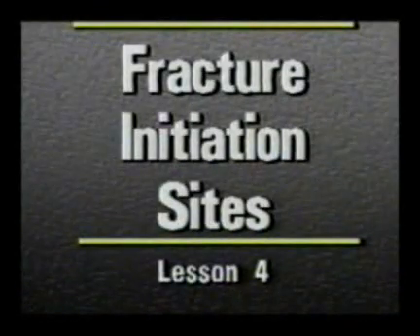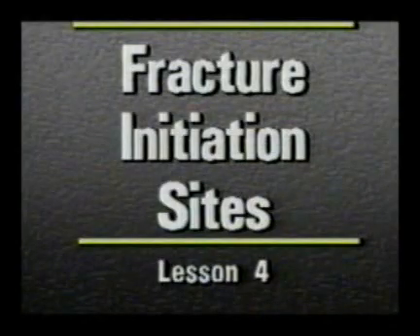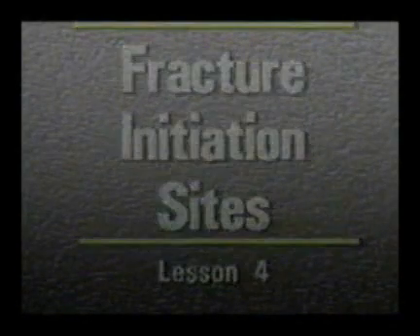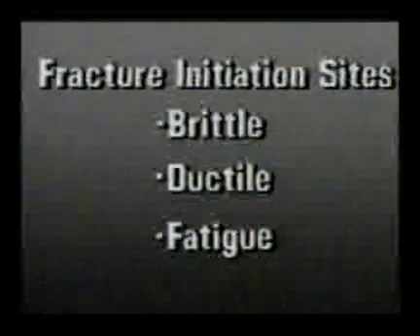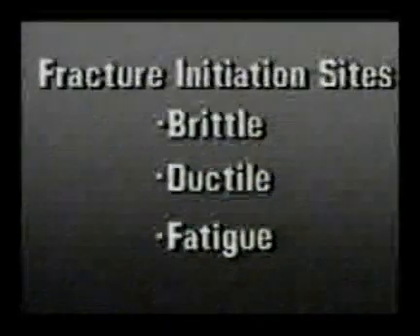Now that we can identify the various fracture types, we will learn to determine where cracking started. This is called locating the fracture initiation site. It is important to find the initiation site because it can reveal the reason why cracking started, regardless of fracture type.